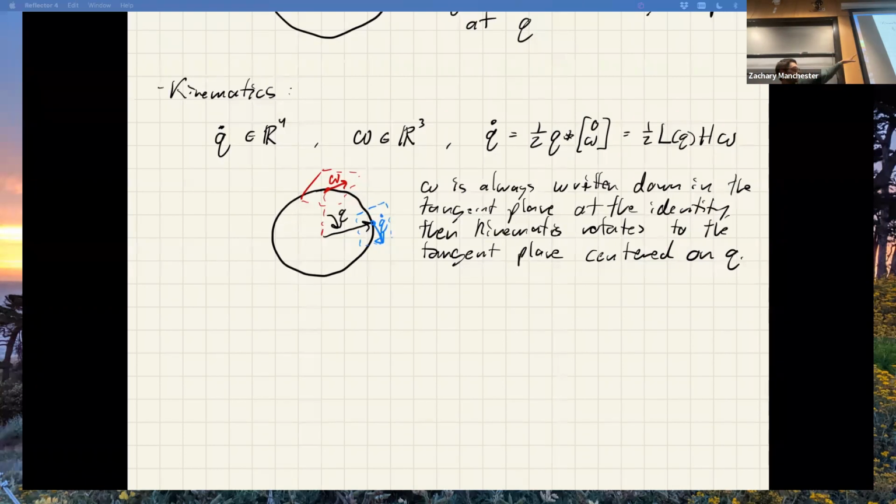If I have a gyro measuring omega and I want to dead reckon, say I know my initial attitude Q and I have the gyro, I just integrate that up and predict my new Q after a little while. That's how you do it. Is it the integral of accelerations in the XYZ direction? No, it's not acceleration either. It's angular velocity. It's what a gyro measures. If I strap a gyro onto me while spinning, it's what that gyro says. It has XYZ components.